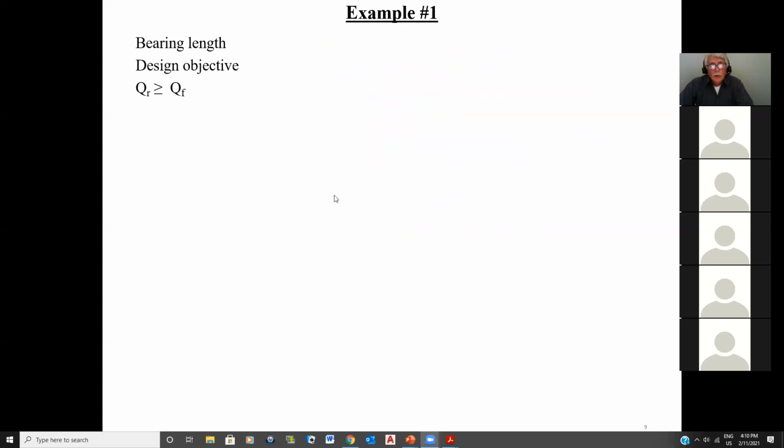So here we go. QF is equal to VF, 33.12 kilonewtons. And then I know that I said KD is 1, KS is 1, KT is 1, and therefore no modification factor. I can go straight to the bearing, okay? And I know that the big QR, which is the small QR times the bearing length, has to be greater than my QF value.